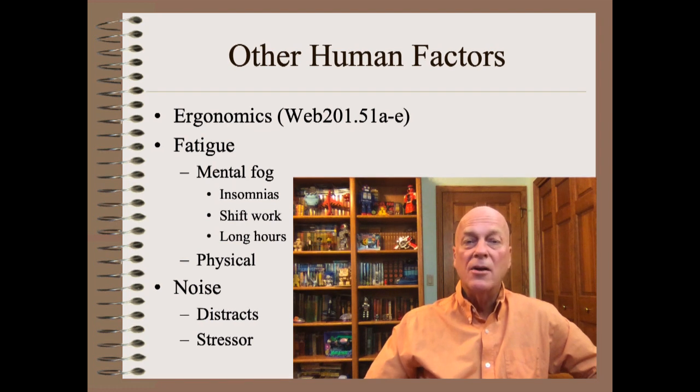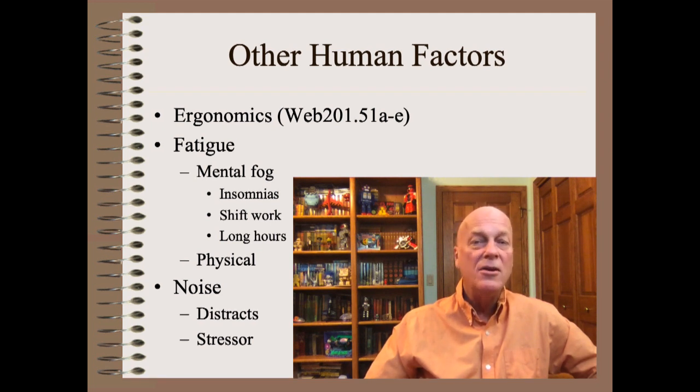Long hours are trouble as evidenced by countless accident studies. The FAA allows pilots a maximum of 9 hours of duty during the day and 8 hours at night. This must be followed by a rest period of no less than 10 hours, of which 8 hours must be available for uninterrupted sleep.